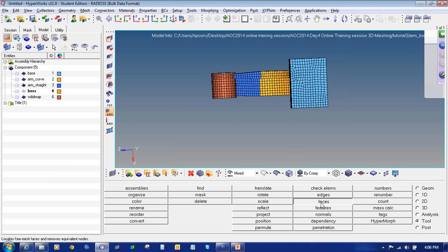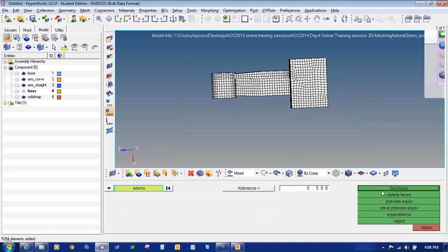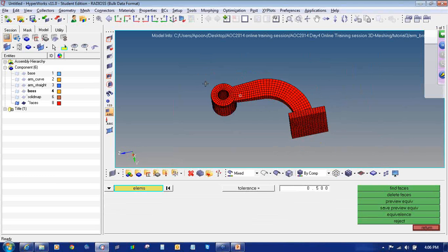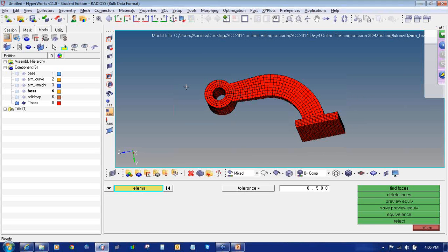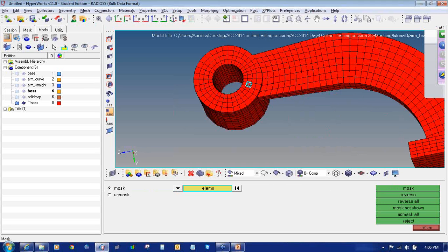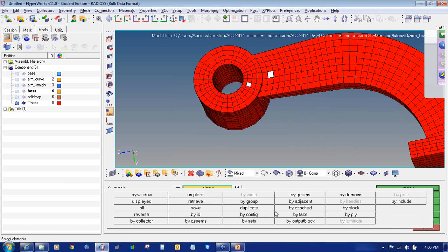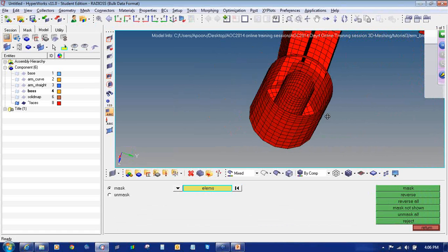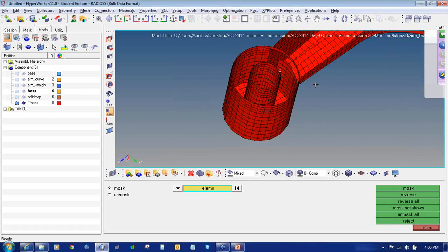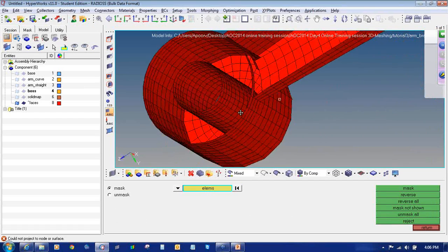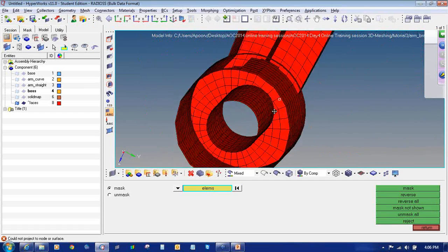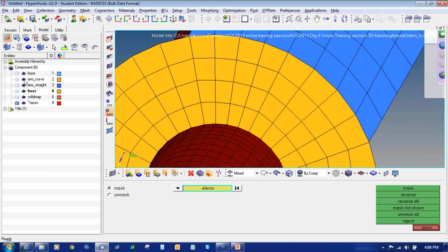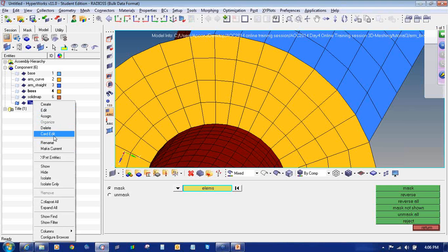Again I will go to tools, faces, click on find faces of these. Again we will check it has to be hollow inside. So mask, elements, by face, mask. So you can see some portion is now hollow, but some is still missing. So we have to equivalence all these. So we will again delete it.